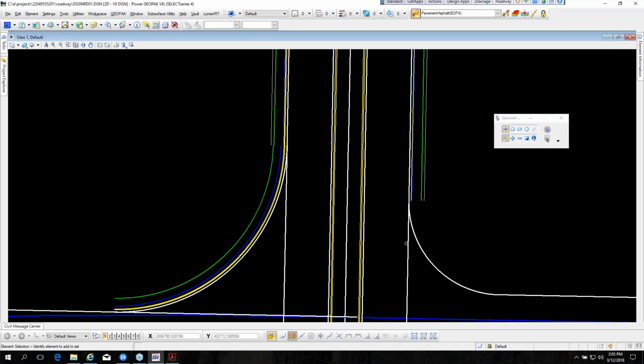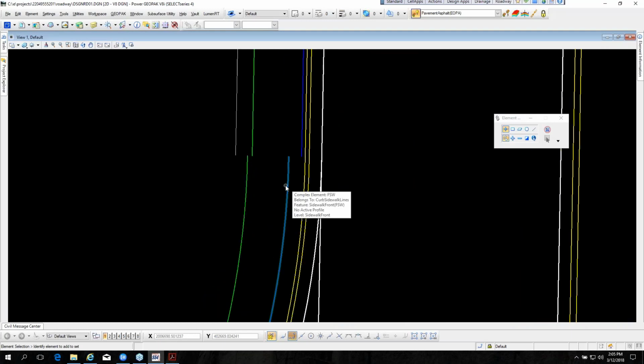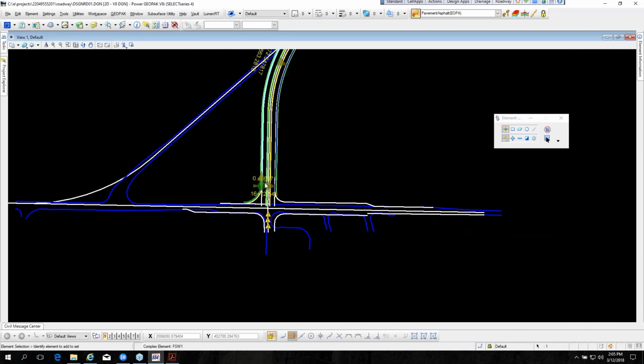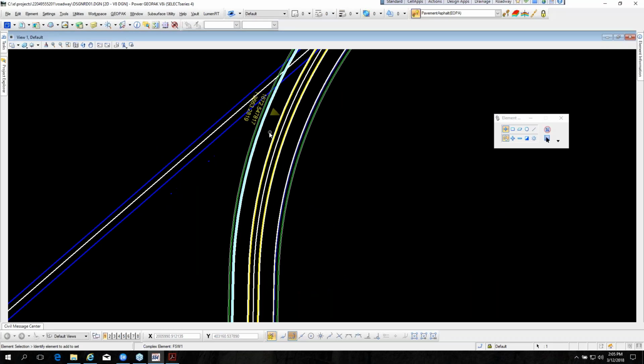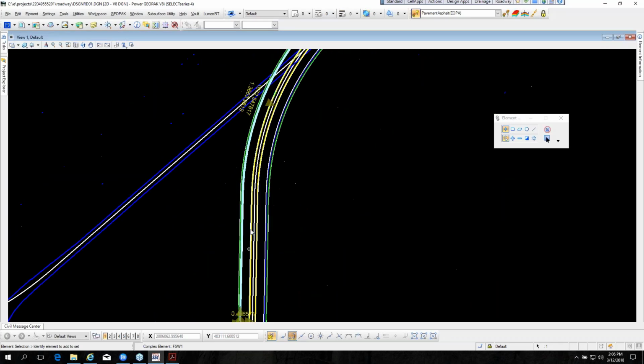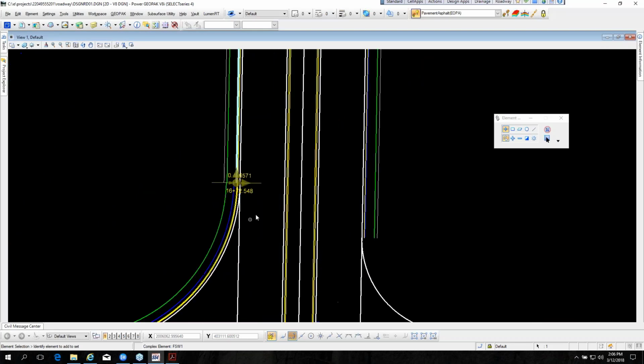So do an F6 to get out of that tool. And then we want to adjust our sidewalks. So I need to come back, looks like to this guy. I'm just going to leave that. Adjust our sidewalk back to 0, and adjust this out to -6.